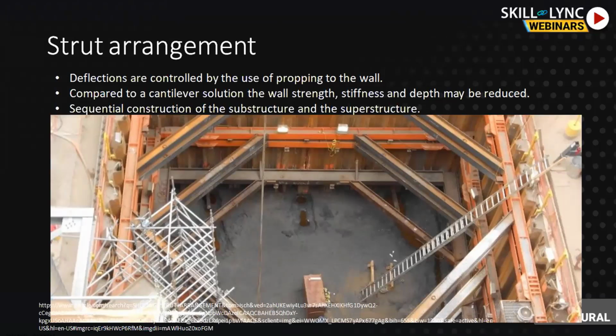Beyond that, you need a proper arrangement, a strut or anchor system, for controlling the deflection, or else the stability of the structure is not maintained. So we need a prop system for maintaining the stability.